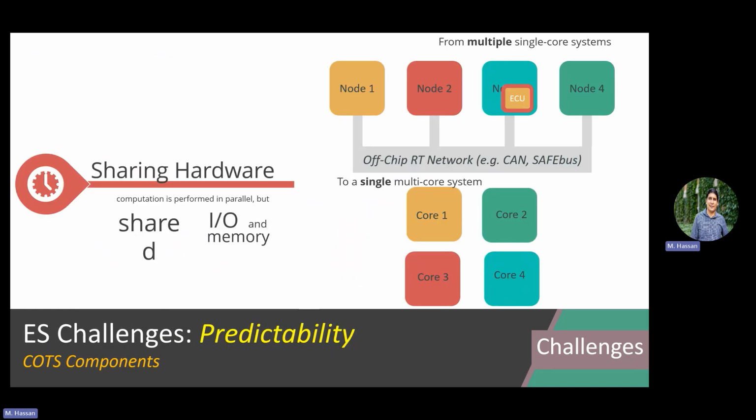If we go to this system here, assume that the radio unit ECU is in this node. We call these nodes in automotive. And assume your engine control is this node. Now, this one is fully secure. It's sometimes called air-gapped: it has no connectivity at all, so it's safe. But this one I can access through the radio. It has some connectivity. So they hacked into it and used it to send malicious CAN messages on the bus to the engine control to stop it. If you look at the root cause of the issue, it was the shared network between the critical and the non-critical task, between the secure and the non-secure task. Good?